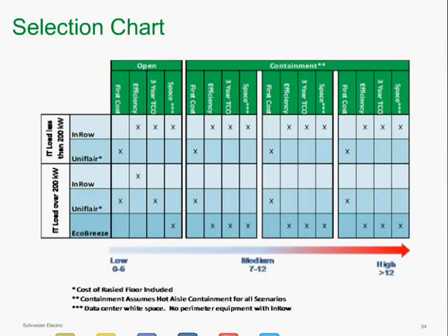And we used both open systems and contained systems, and we really broke it down into first cost efficiency, 3-year TCO, and also space. And just as an example, if you're operating a small data center and efficiency and 3-year TCO is really your primary objective, we found that in-row cooling solutions were really the best starting point for a small data center with these types